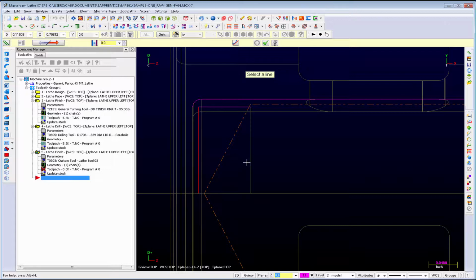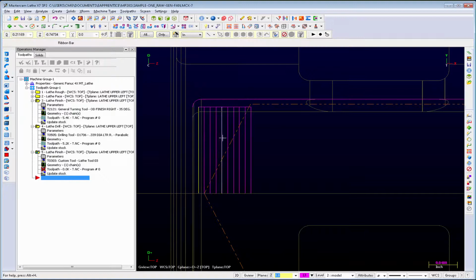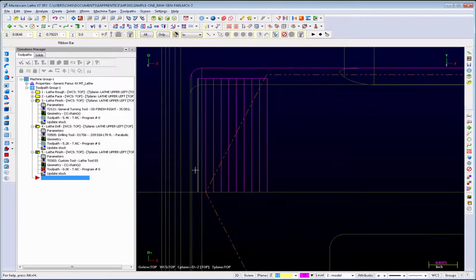So what I'm going to do is just create a line parallel, and we'll say that we want to take, I don't know, 10 thou passes because it's a small boring bar. So we'll lock that value in here. I thought there was a way to easily apply that. And I probably just could have also translated this a number of times. There we go. And we'll get rid of that one. Actually, no, we'll leave that because of the radius.